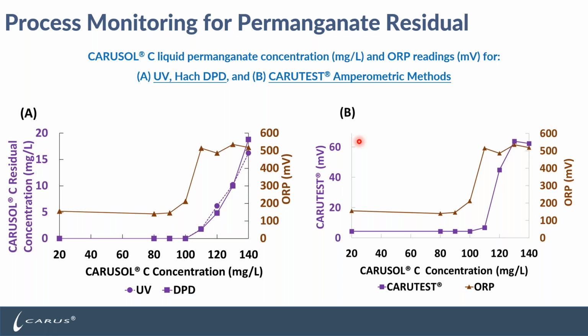DPD online analyzers are readily available and easy to use, so this method would make for a good process control to ensure no overfeed of permanganate during the treatment process. The plant at Oceana Gold's Haile Gold Mine continues to carry out spot tests several times a day using this really easy approach.